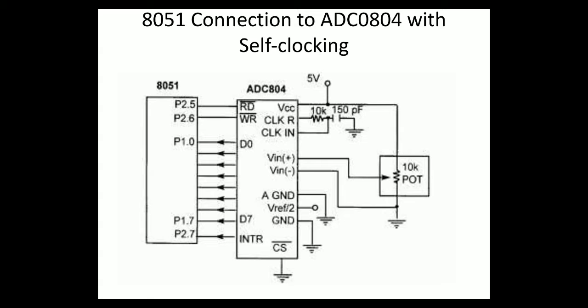Therefore, we need a time scale that says after what time the analog signal must be sampled, or in other words encoded with a new value, and that is called time stamping. To maintain this sampling time, we need a clock frequency. This clock frequency keeps track of after what time the analog signal needs to be sampled, and therefore every analog to digital conversion IC needs a clock as one of its important functions.